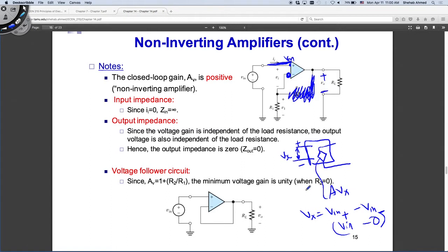Of course, from our op-amp characteristics, our output voltage in open loop configuration, this is open loop configuration, there is no feedback. In open loop configuration, the output voltage is equal to A times Vx. So A is a very large number, and Vx has a value. So the output will be large. The op-amp output is being controlled or driven by its open loop gain in this case. We're okay with this? So now, if I want not to have this, because this is not useful for amplifying, subtracting, adding, it's only useful for comparing.